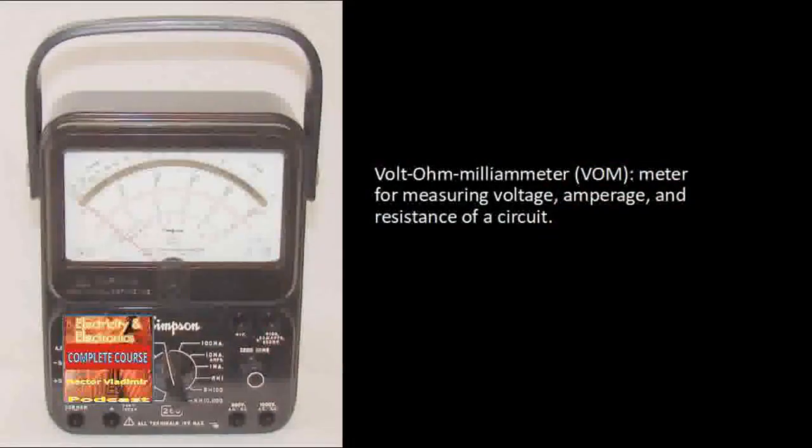The volt-ohm-meter, milliammeter, or VOM. A common and simple multimeter used in electronic circuits is the volt-ohm-meter, or VOM. A VOM is a voltmeter, ammeter, and ohmmeter all in one. The VOM has the advantages of being inexpensive and portable. It does, however, usually have a low input resistance in ohms per volt on the lowest voltage range. This factor can cause accuracy problems.